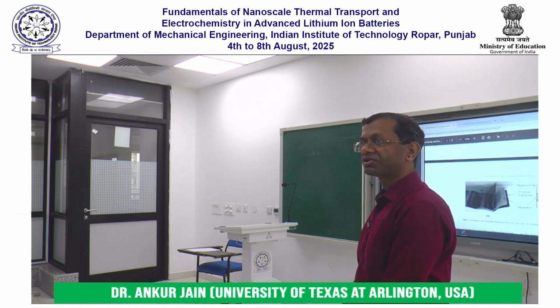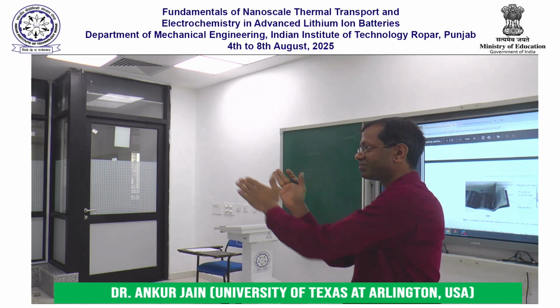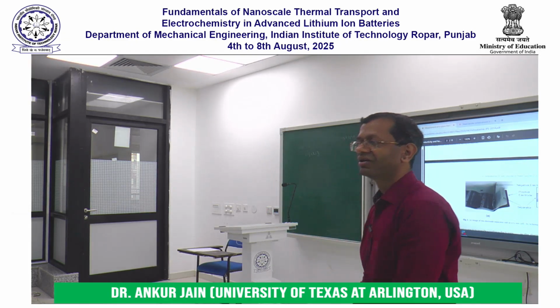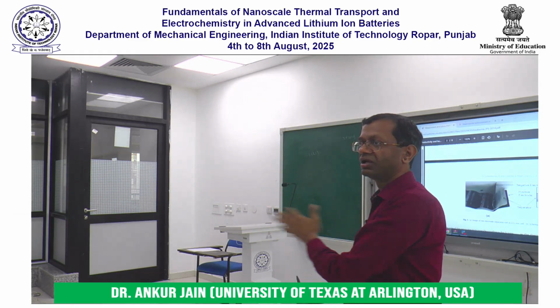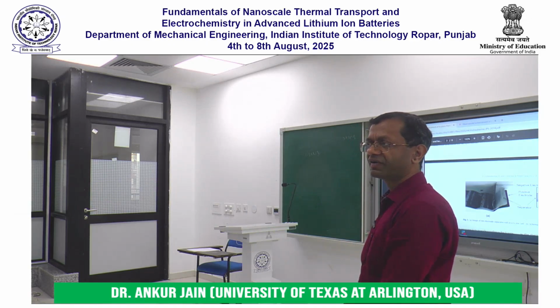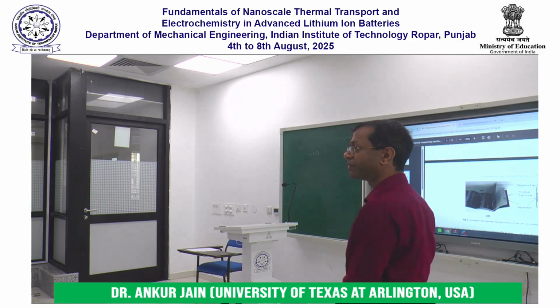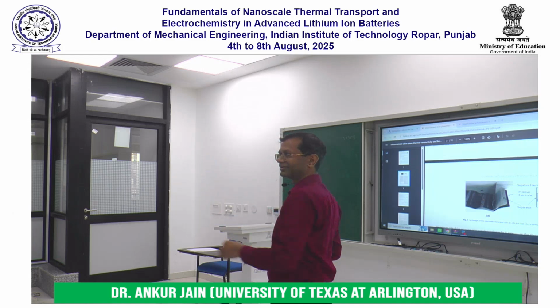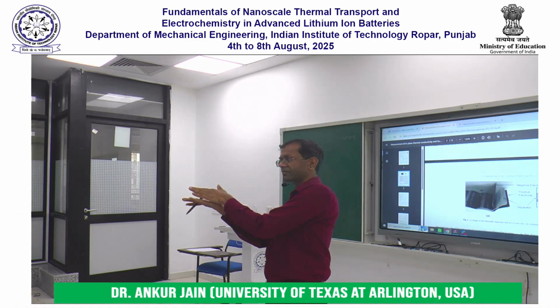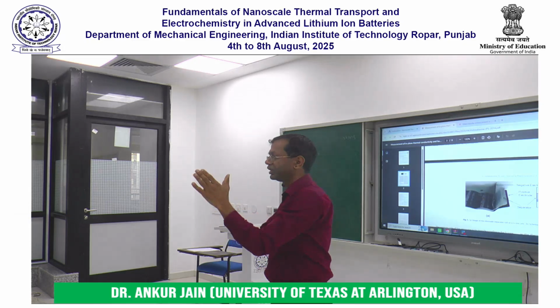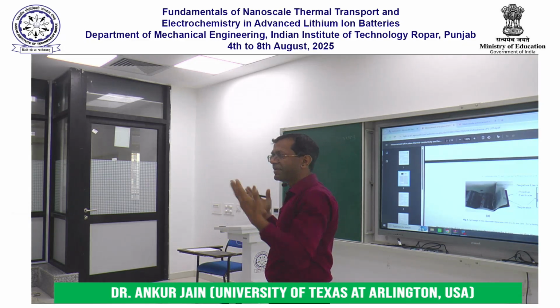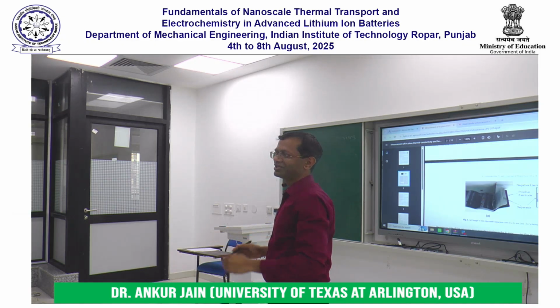Why? Because any material that I place between them can hinder the flow of lithium ions. I want lithium ions to pass through in an uninhibited fashion, which discourages me from putting glue between the two, right? But the problem with that is that if you take two materials, no matter how hard you push them into each other, they may or may not adhere to each other in the true sense of the word.